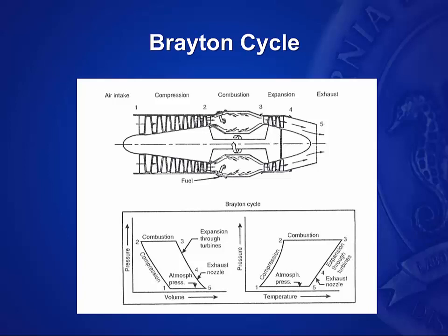It is also that the combustion takes place at a constant pressure. Now, with the internal combustion engine, you're compressing the air in the cylinder, and near top dead center where you have the smallest clearance volume, fuel is injected or is ignited within that very small confines. So it is a very high pressure, high temperature burn, and it takes place within fractions of a second.